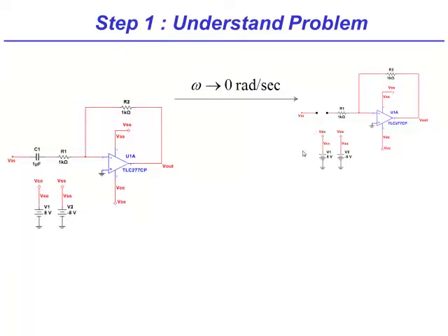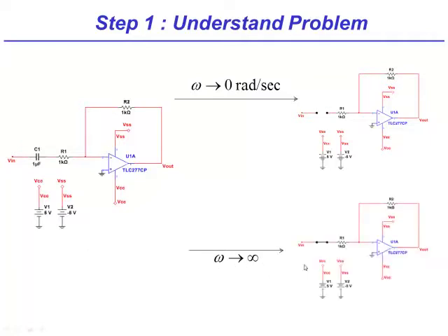I have heard of expressions like capacitor in the current path blocks DC. So this is what it meant. Correct. Okay, at high frequency, the magnitude of the capacitor impedance is 0, and hence the capacitor acts like a short circuit. So the circuit is essentially a high-pass filter.